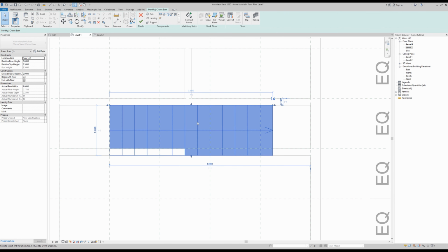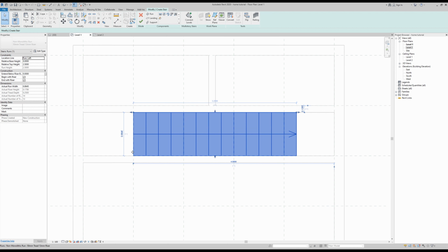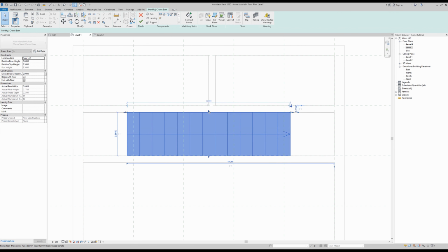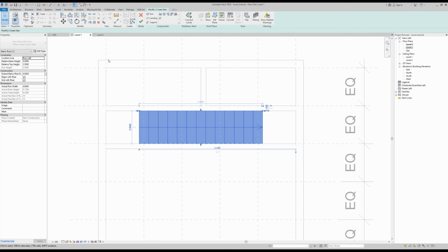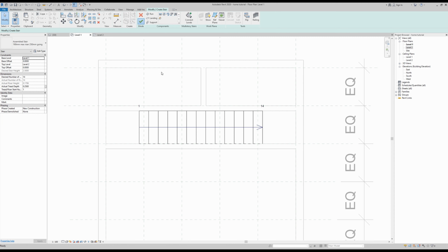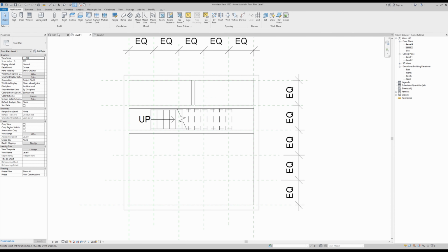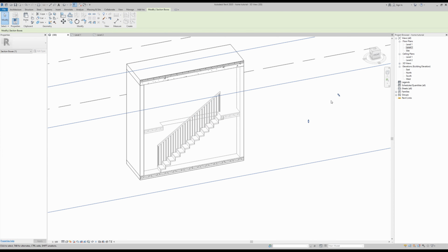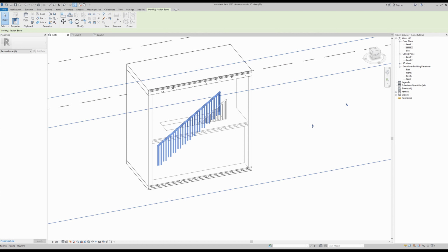And you might notice that this width is quite large, so let's just bring that back to this side here, so that it properly fits the space. Then MV for move, and let's bring it to the center around here, for it to have equal spacing like that. Okay, then we can close our stairs, and if we go into 3D mode, from time to time these railings might still be around. Still, you can once again click them and remove them.